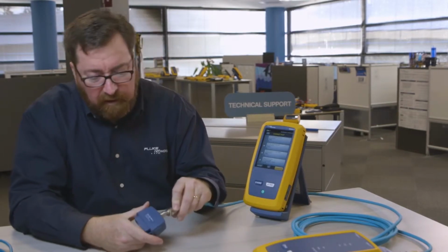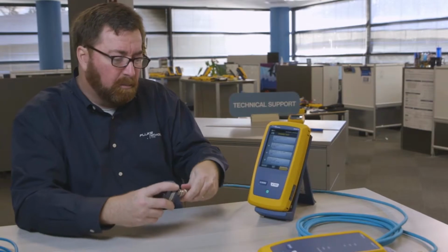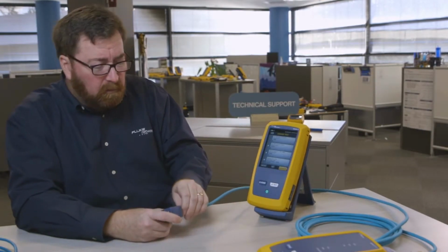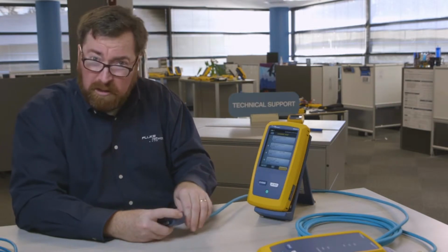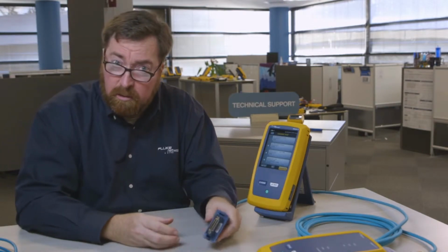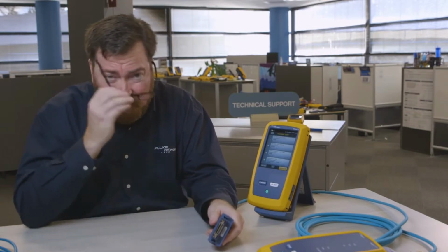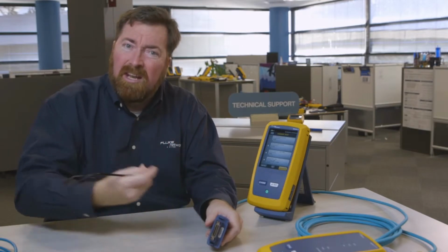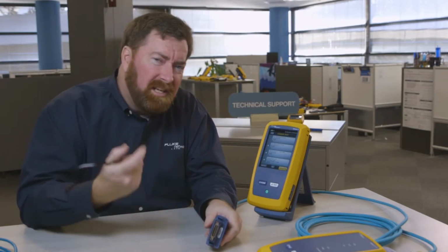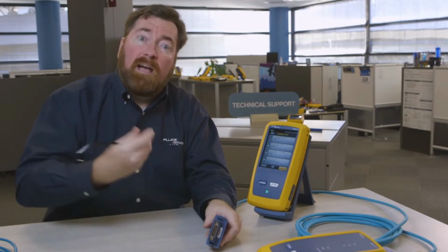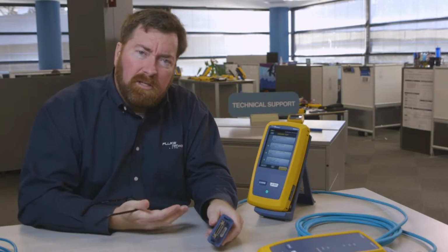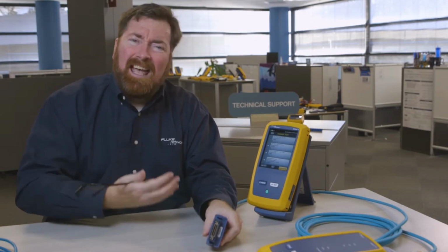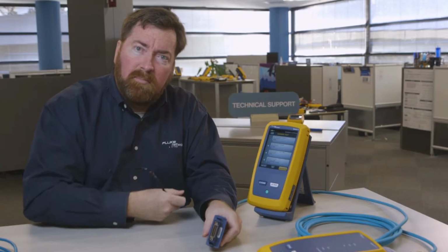It helps to have this M12 X-coded adapter to put it on, but now what test limit am I going to use for this? Well, from the building world, we're used to talking about the Telecommunications Industry Association, the TIA 568 standard. But the TIA 568 standard is for buildings, not industrial environments. TIA does have a standard. The 1005 standard is designed to be used in industrial environments. What I found is it's not as well known as it could be, so let me explain it to you a little bit.